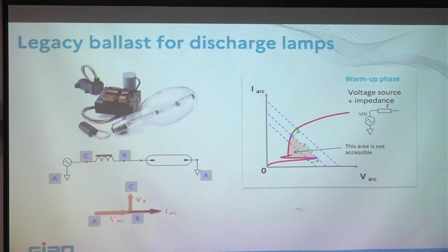But you have to pass through the inductance, and finally what you see from, I think I inverted the letters here, you see a phase shift introduced not by the lamp, but introduced here by the inductance. And this cosine phi here, today the IEC standard says that we have to keep it above 0.95 or 0.9, okay? Then you have to compensate.